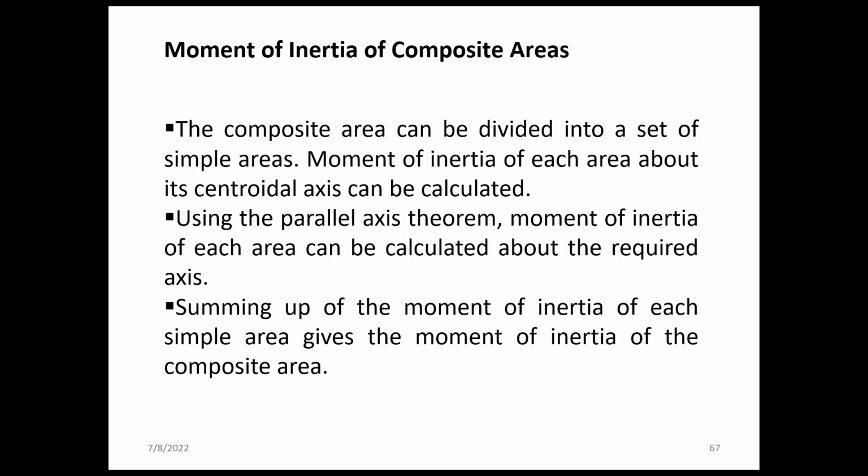So, coming to the fourth video of this module, the moment of inertia of composite areas. Till now we have studied regular plane areas like rectangle, triangle, semicircle, etc. Now we are going to find the moment of inertia for composite areas, like we did for the centroid calculation for composite areas. Here, the composite area can be divided into a set of simple areas.